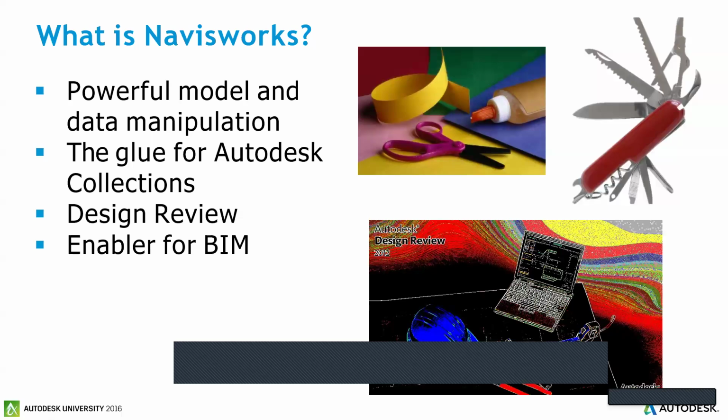In this way, it all together gives you a proper way to work with multiple disciplinary models. Coming back to the part of BIM where it enables the BIM process, a basic part of it is that once you have Revit, there is an exporter named Navisworks NWC exporter. You need to install that plugin, and once installed, you will get an option of exporting the Revit model directly from Revit to the Navisworks platform.